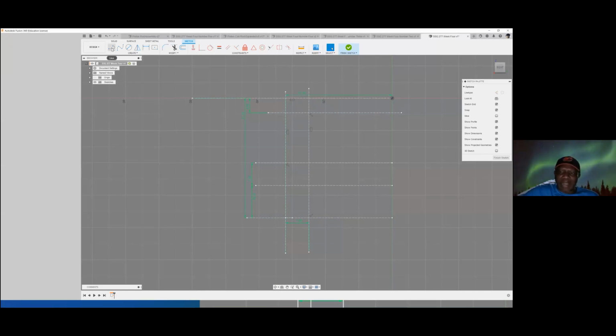Then you can go back and use the line tool to do the profile. You do the profile this way. You start from a point and you draw a line to the next point. Okay? So once you've drawn a line to the next point, you can use the marking menu to bring up repeat line. So it gives you repeat line, and you can start from here again, and you get to the next point. Then marking menu, repeat line. You get the marking menu by right-clicking. You go from there to the next point. Again, you use the marking menu to repeat the line.